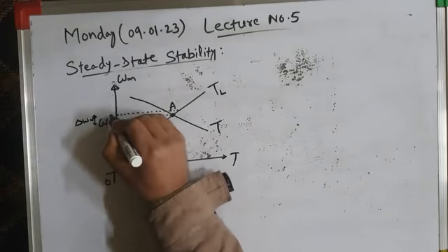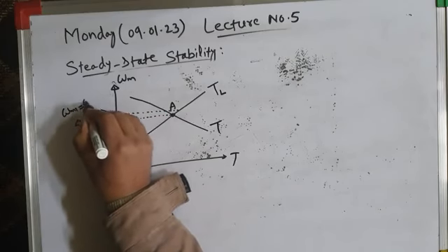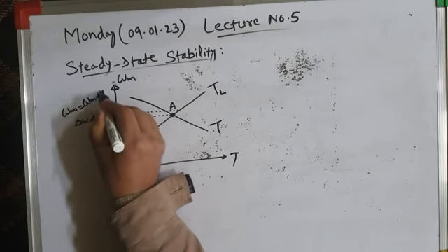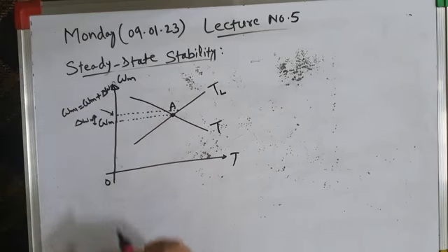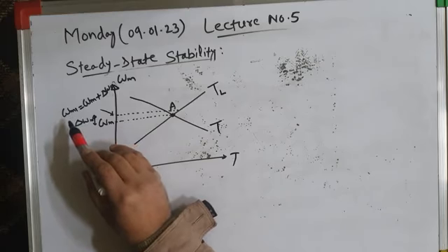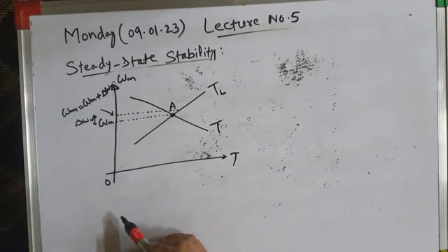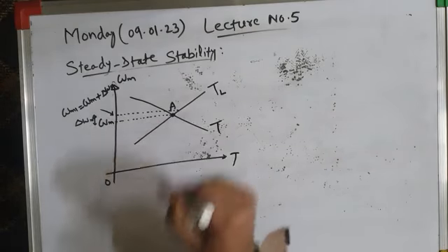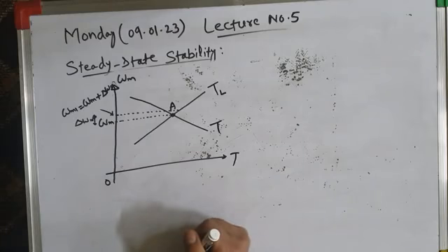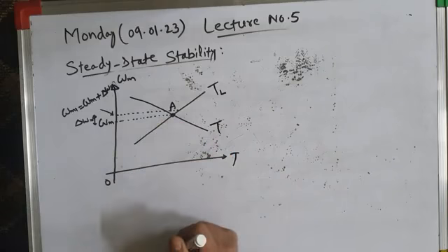So what is the new speed? The new speed is omega m1, equal to the original rated speed plus the speed perturbation, delta omega m. So omega m1 is equal to omega m plus delta omega m. Now this operating point will be stable, or the drive will be operating stably, only if the operation returns back to the original operating point. Let's see whether this happens or not.